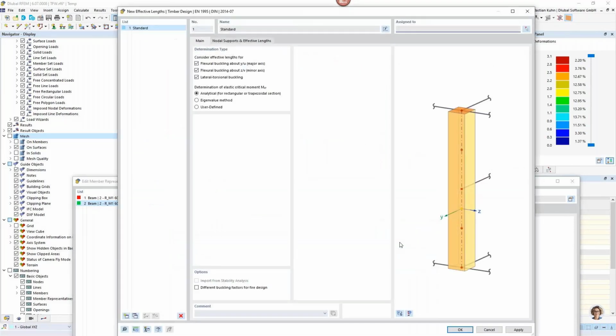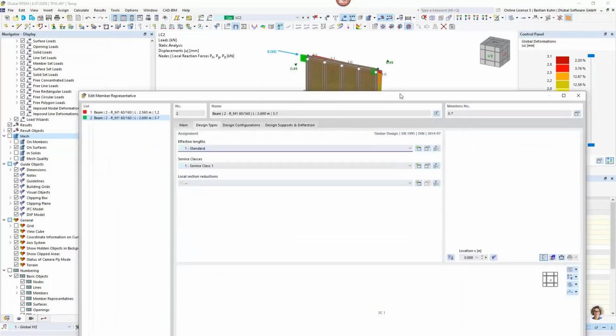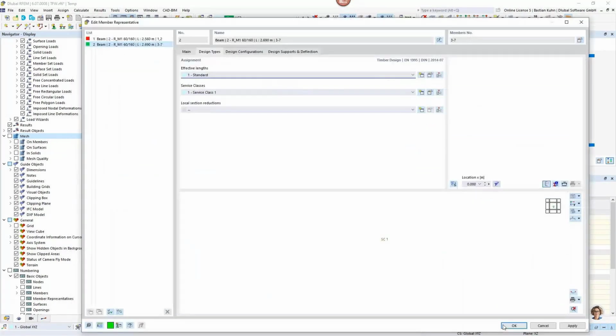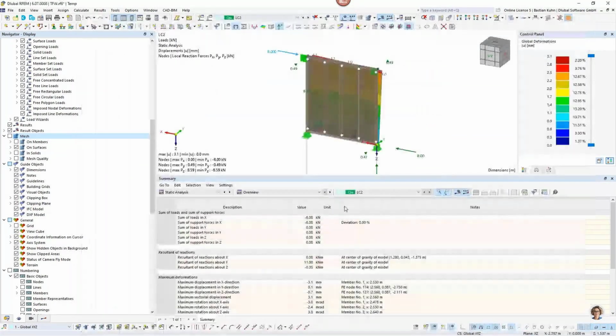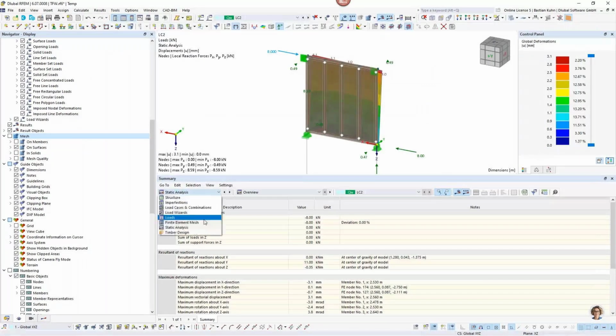And then, of course, effective lengths, what we do not verify, lateral torsional buckling. We even do not need to verify the buckling about the minor axis, because that is covered by the planking or by the sheeting. But just for the sake of completeness, we are verifying it.